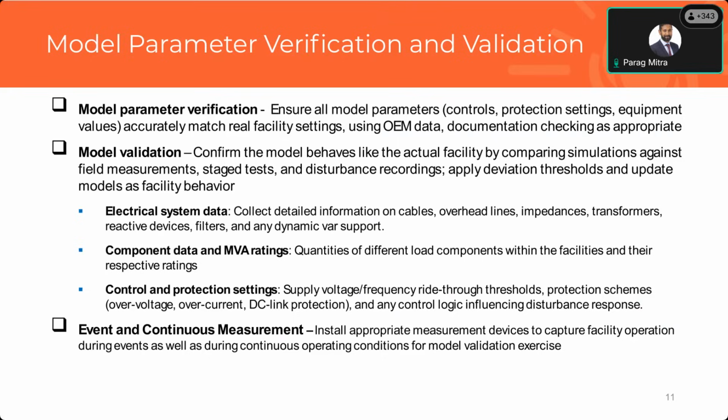Now, for this validation exercise, there is a need for event and continuous measurements. The event-based measurements are things like DFRs that allow us to record the very fast dynamics, and once those events are available, we can use that event data to validate the model. If the parameters are not tuned properly, that provides us an opportunity to refine the parameter tuning so that we can replicate the facility response.